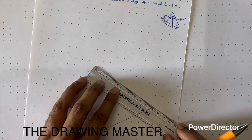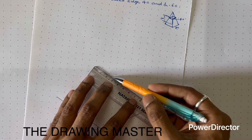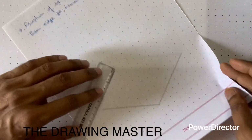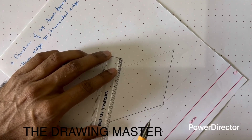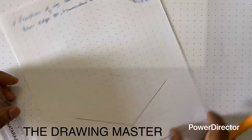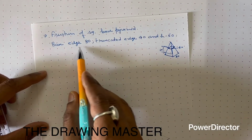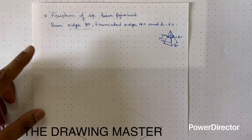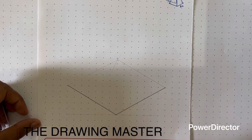This line will be a continuous thin line because this is the rear edge of the frustum. This is not visible after the construction of this object. So now we have created the base of square with edge of 80 mm, which is just like a rhombus in isometric view.